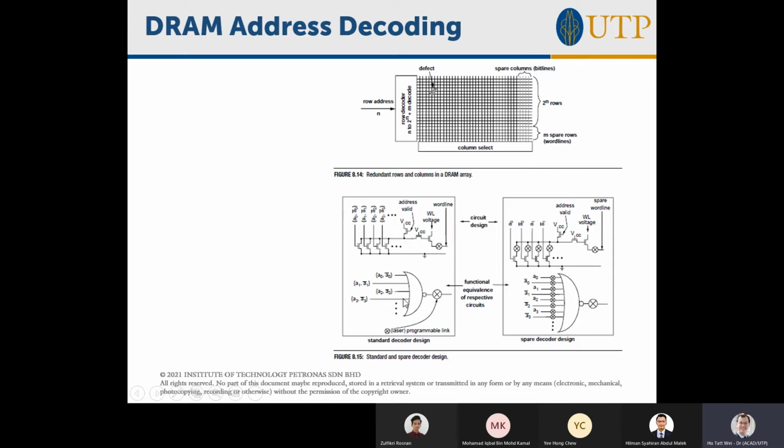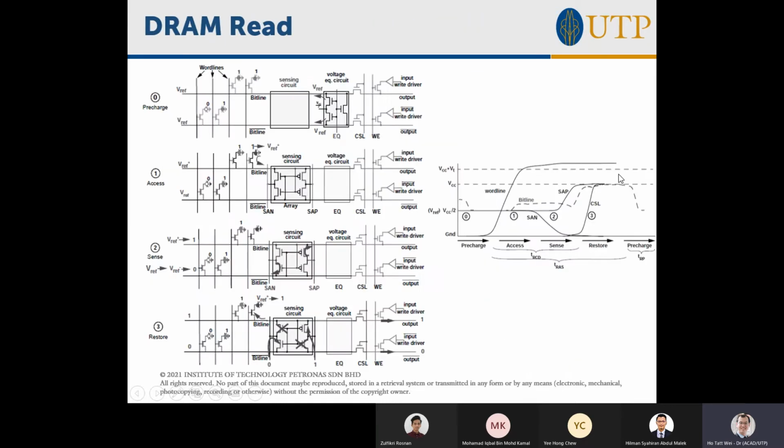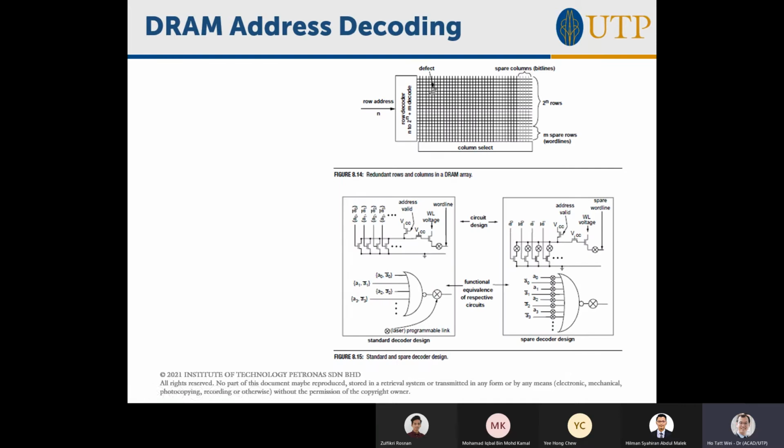That's the one, okay, if you want to select row 2 and row 3 and all that. So you have this huge decoder circuit, one for each row. And later on, you also have a similar circuit for the column select. The column select is basically you're choosing which of these sense amplifier outputs you're going to send up to the bit. Okay, so there are two parts to it.